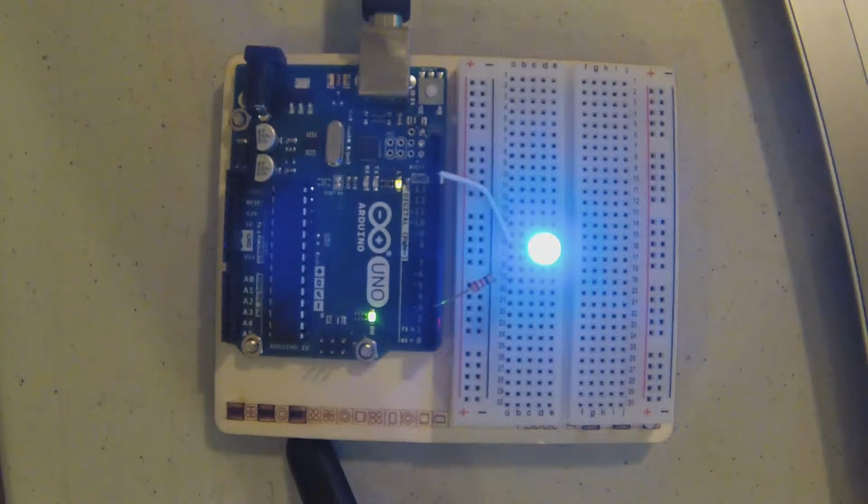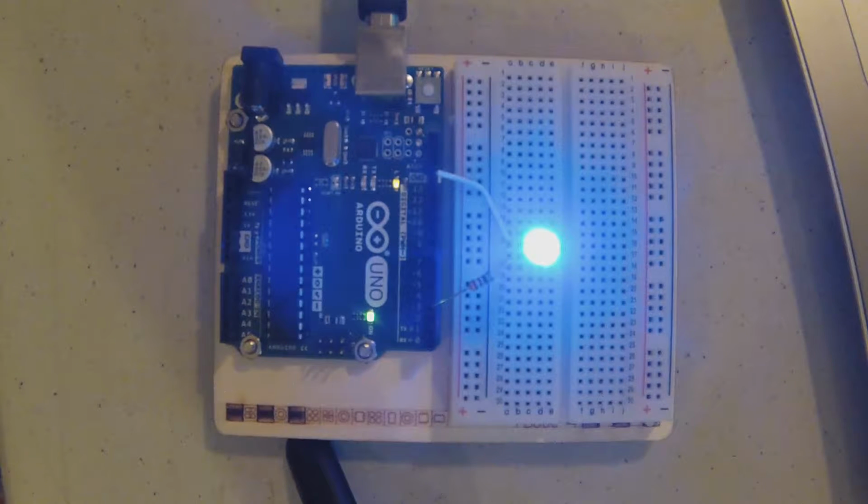Objective 1, 50%. Using the same circuit by simply changing the value of the analog write into the pulse width modulation, we alter the brightness from 25% to 50%. Objective 1, 75%. In this objective, we've altered the number for the analog write pulse width modulation to 192, roughly 3/4 of the maximum pulse width modulation that we can input into our code. In Objective 4, we've increased the pulse width modulation to 255, resulting in a 100% duty cycle.